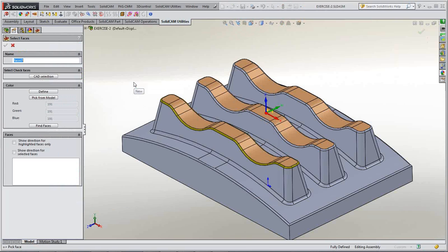And this is especially handy if you can get your design department or whoever does the modelling to colour certain surfaces for you. Then you can pick things by colour. If you've got things that are different colours all over the place, it helps you pick the geometry, especially on 5-axis work where it can be quite complex, quite time consuming to pick all the different facets and faces that make up the contour that you want to machine.